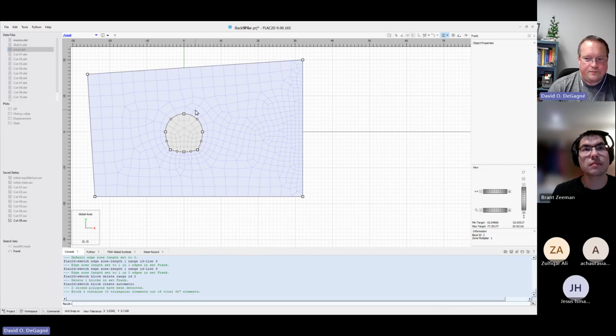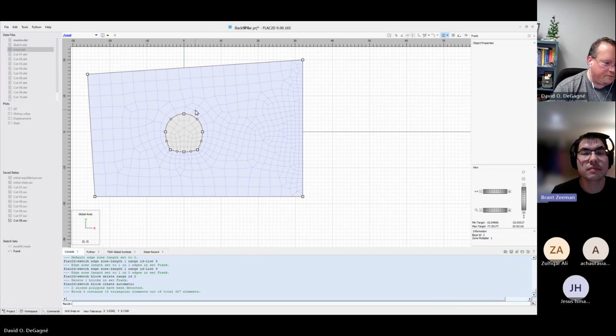And if we just delete it and it's high stress, you're going to see artificial numerical effects. If it's low stress, not really a problem. But if it's high stress, the model can't really keep up the way the Earth does. So anyhow, we call that zonking at Itasca, or the command now is referred to as the relaxation or relax command, and it just lets you do that gradually.